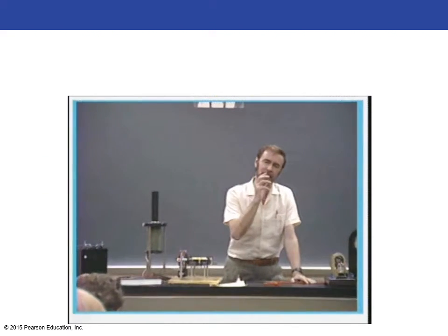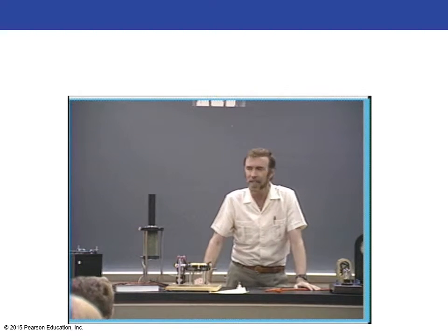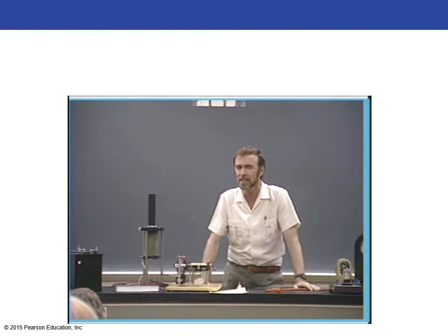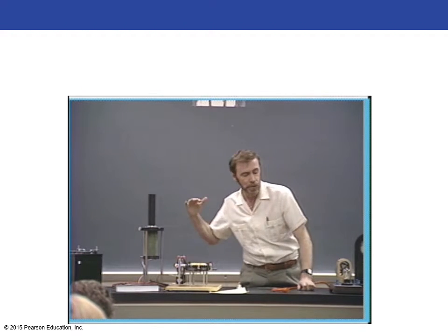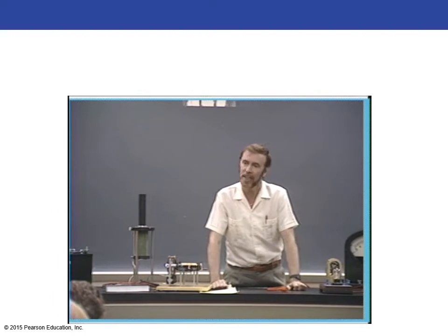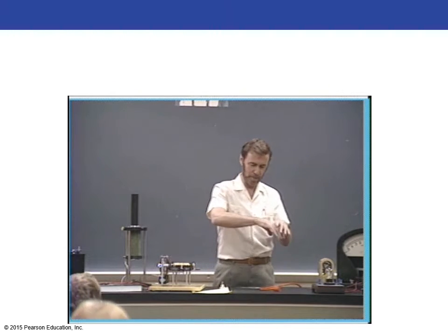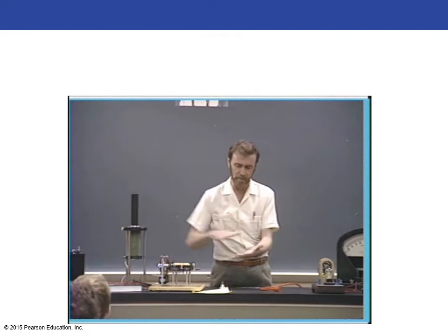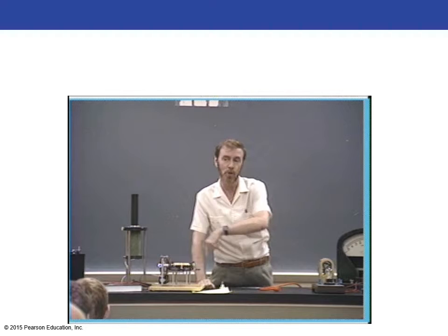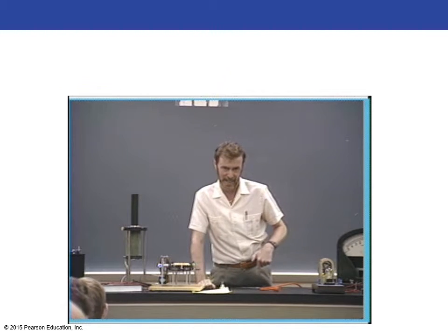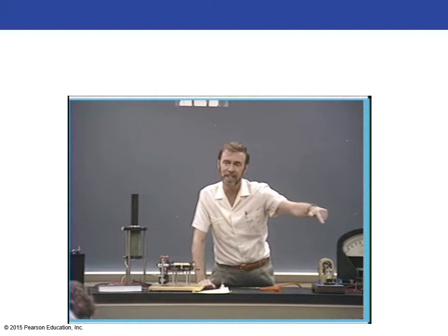Hey, you know what is a neat application of electromagnetic induction? It's just been the last few years, and that's the smart lights. When you're traveling down the road and you're coming to the traffic light and the lights change for you. You drive over something and that something changes the lights. They used to put a piece of rubber tubing out there with compressed air, and it would make a little pulse of air, and that changed the light, but then the rubber would wear out. What they do now is they bury in the road a coil of wire. Okay? Coil of wire buried in the road.